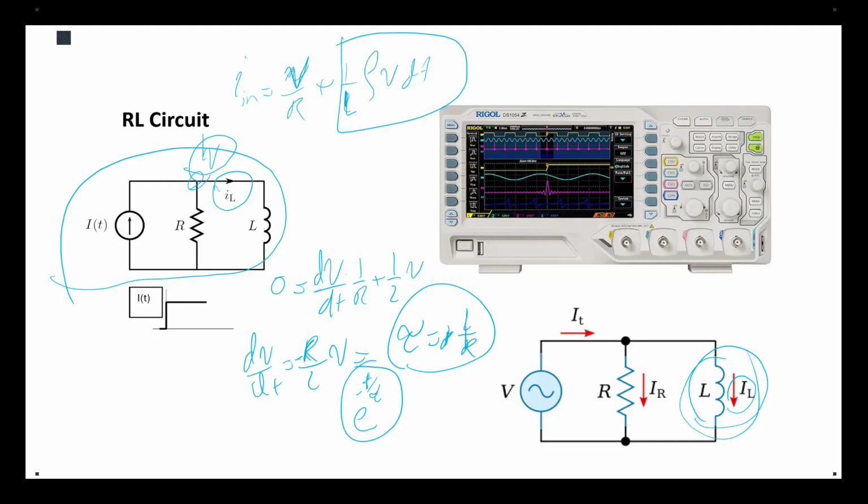What component would change the current to the voltage without adding a nonlinear dynamic or a differential integral dynamic? So you are going to put in a small resistor in series with your inductor, and you are going to measure the voltage across that resistor.